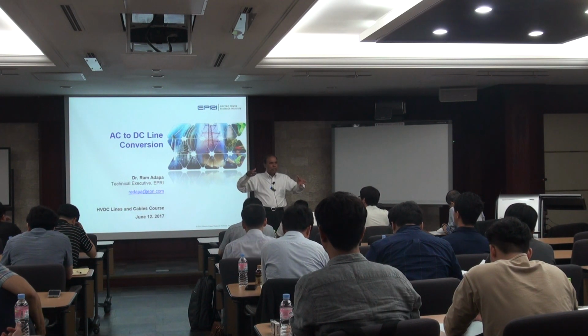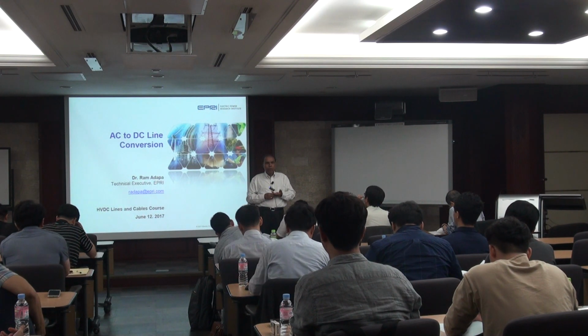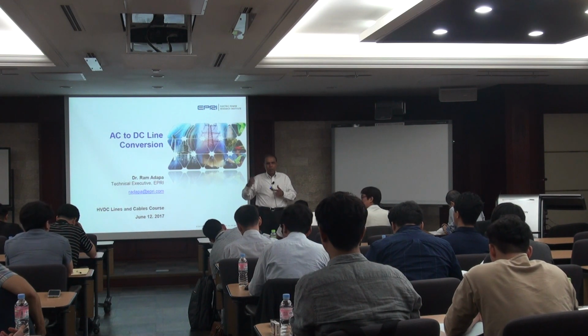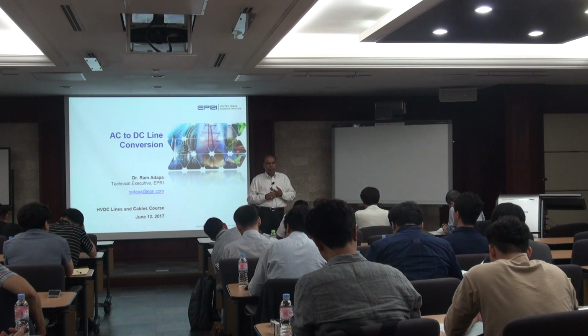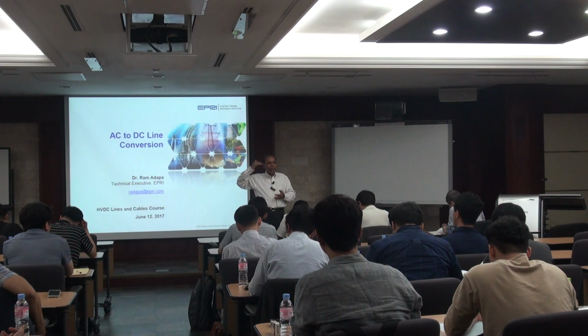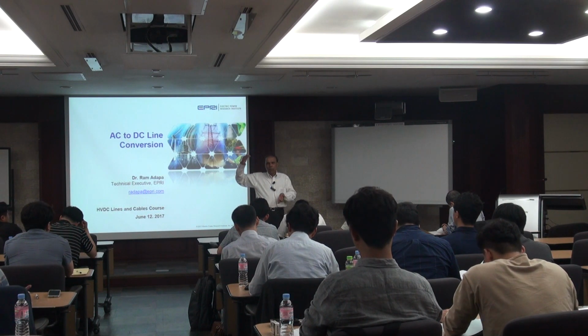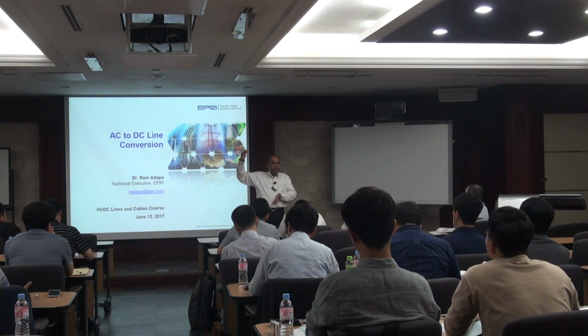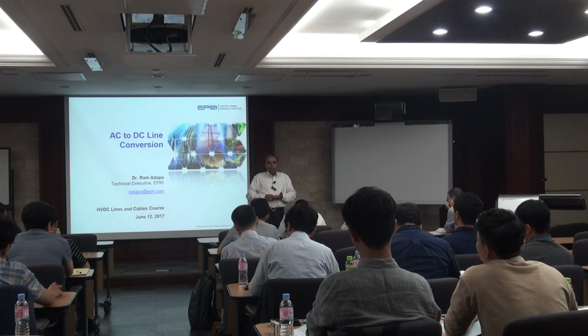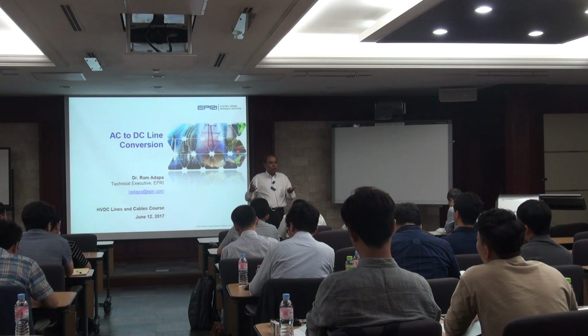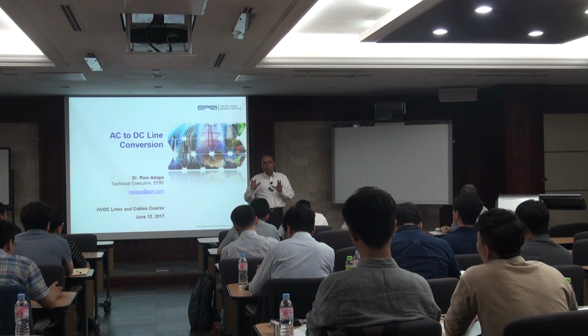Change the insulators, because AC insulators won't work for DC. DC voltages are different, constant DC voltages. And you also operate at a higher DC voltage than the AC RMS voltage, so you need more insulators to support that from the pole to the conductor. So the ultimate goal is to push more power on the existing corridor.